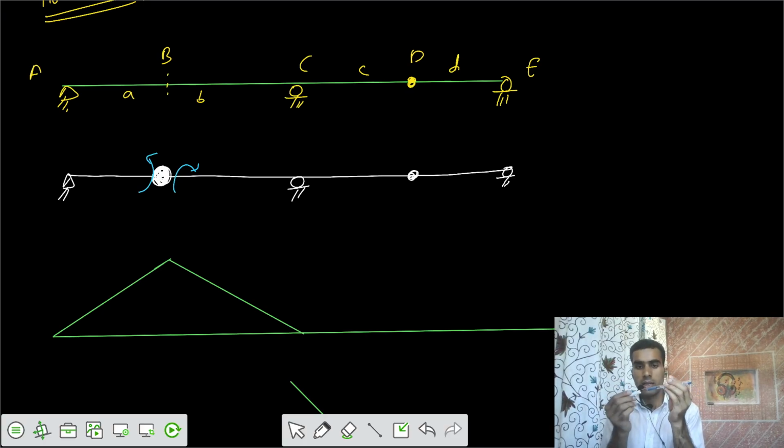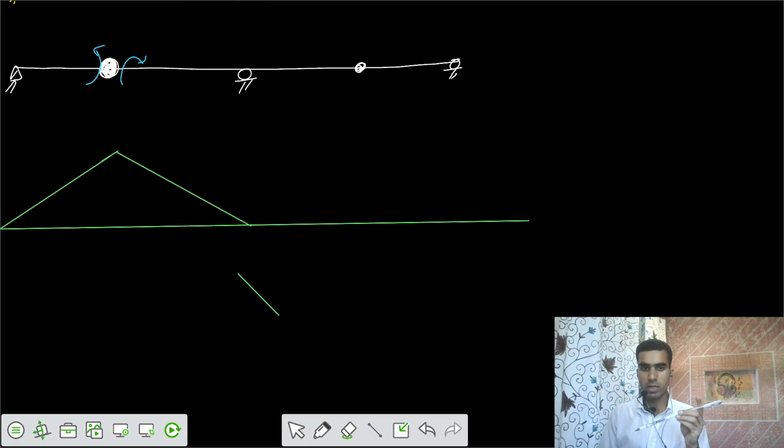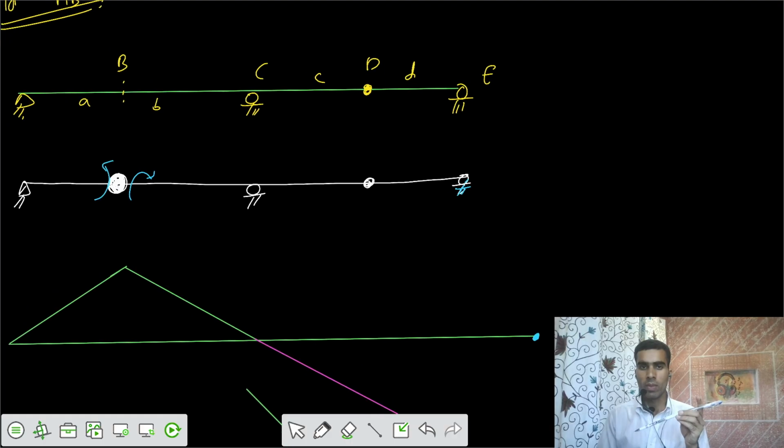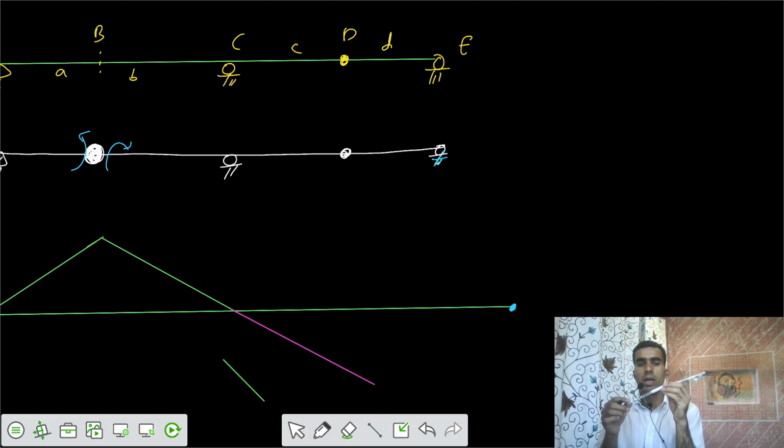now there is point C. After point C, there is point D. At the point D, we have an internal hinge. So that means the profile of CD would be downwards. Up to the point where we have the internal hinge, we have to ensure that this point is at this location because we have support here. That means we have to ensure that there is support at the location of itself. Then after that, at point D, we have an internal hinge.